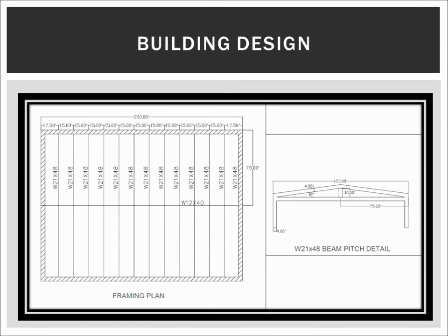For our roof design, we wanted a design that was simple because of the limited requirements from the building. The buildings will only be used as a cover from weather for multiple desalination operation processes. Knowing the minimum requirements for our structure, we chose to use a simple king post truss with prefabricated light gauge steel truss. The advantage is that it offers a high strength, yet lightweight roof system that is easy to install.